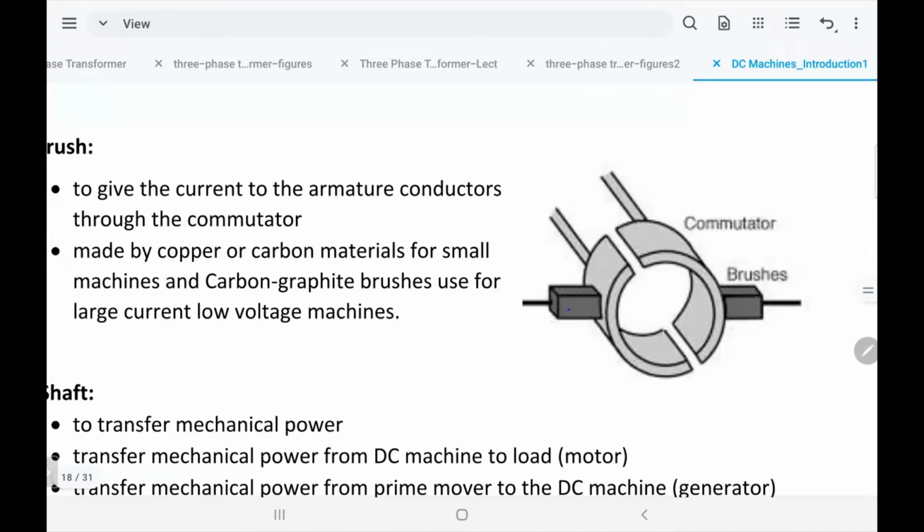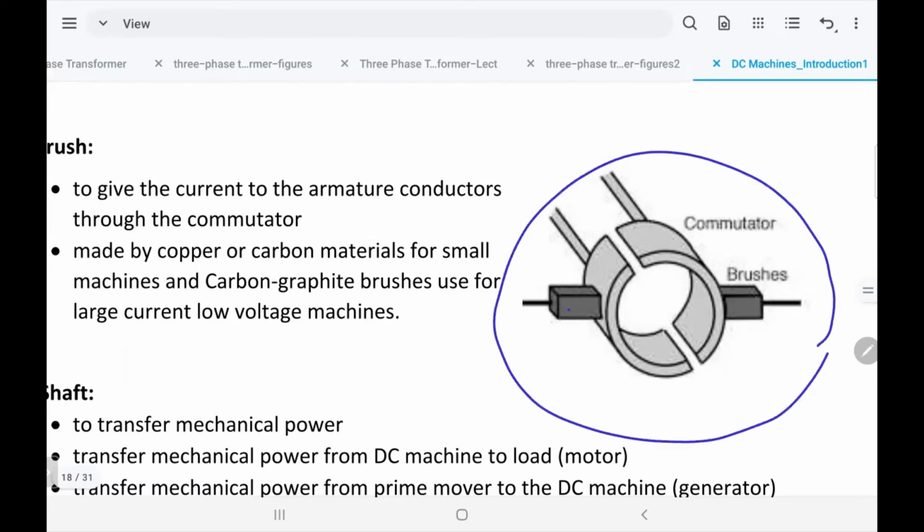When I was a student, I wondered how the brushes could be hanging in the air like that. So I went and looked at the machine myself. That's the stator, right? There is a spring connecting the stator to the brushes. I saw with my own eyes that there is a spring. So when the brush touches the commutator, it is in good contact with it. That spring is isolated from the brushes, which are made of carbon, by the way.